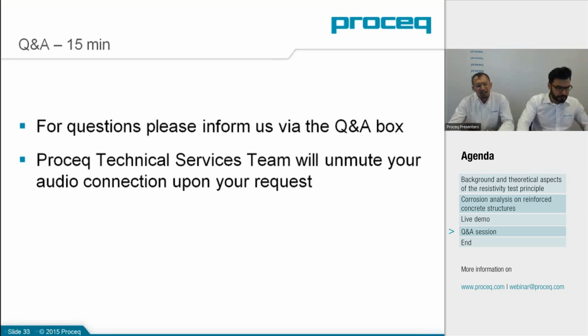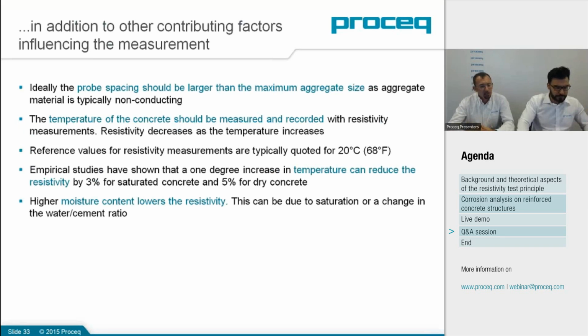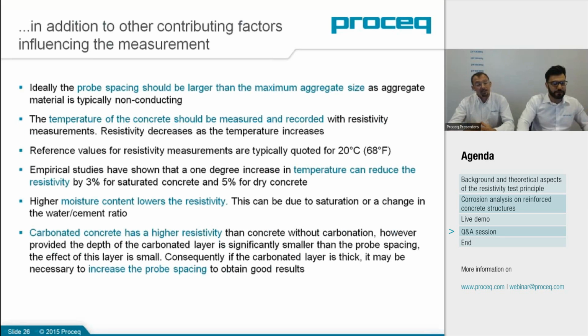The point is that there is no actual modeling of the variation of resistivity over huge temperature intervals. The key point is that we don't really need that, because it will always be a qualitative comparative test that we do on one specific day or one specific week over the structure. So all the different areas of the structure will be affected in the same way. They might be shifted up or down, but just keep track of the temperature. Yeah, exactly. So these are obviously an indication.